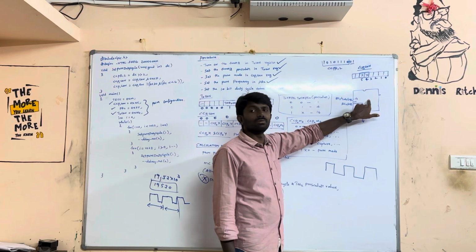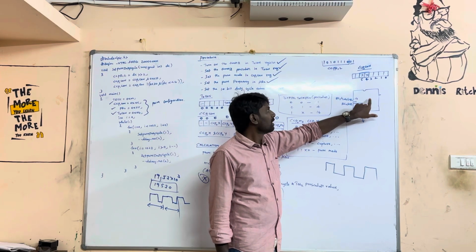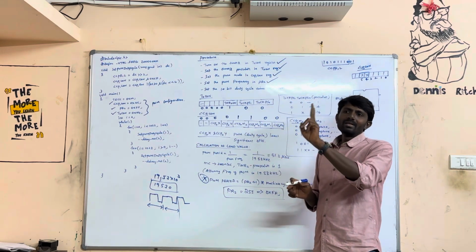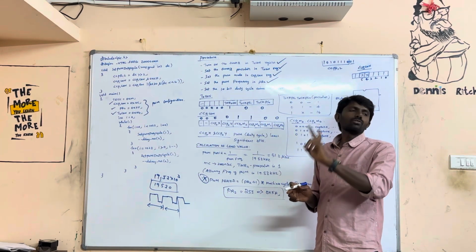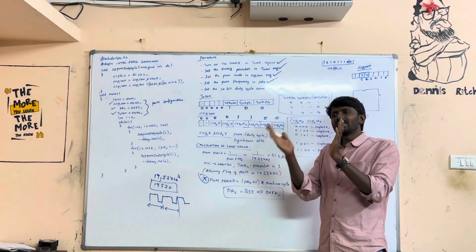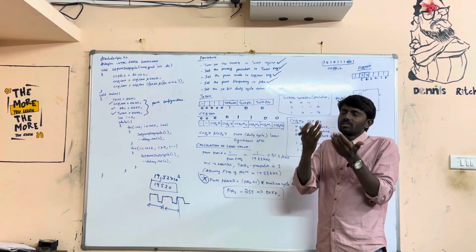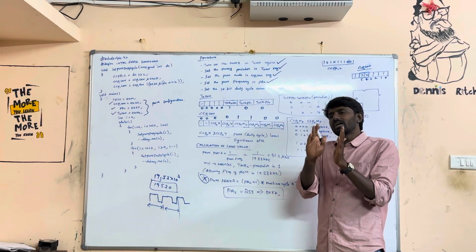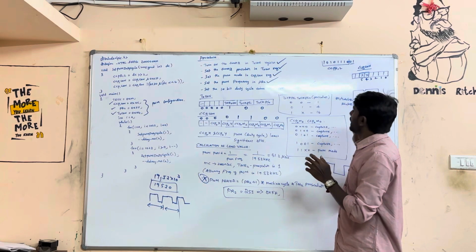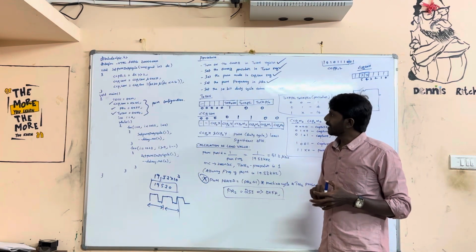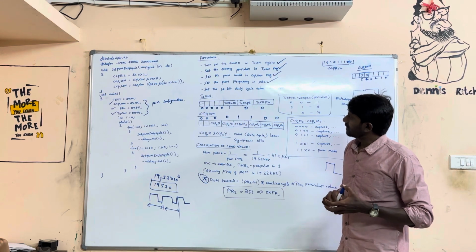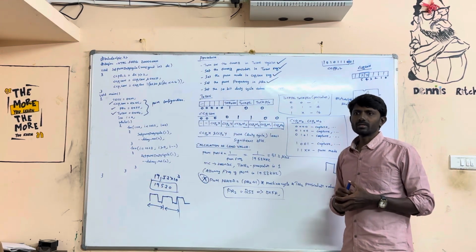What actually happens internally is you set the 10-bit value, which is nothing but the duty cycle. So what is the duty cycle? In one clock we have a T on and T off. T on is called the duty cycle. By controlling the T on, T off is automatically adjusted. However much percentage you give T on, that much percentage of output voltage you can expect on this PWM channel. I think that's it. Almost everything is covered. Okay, now we can stop.